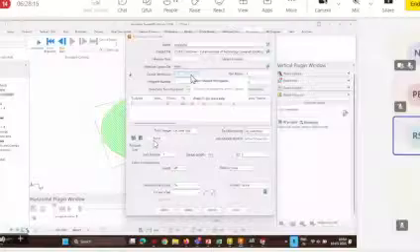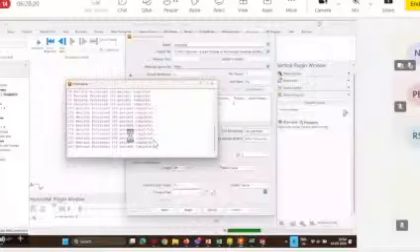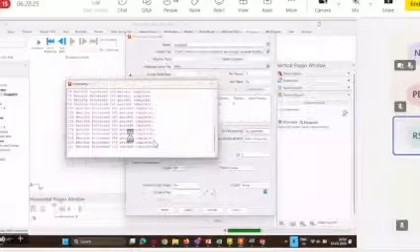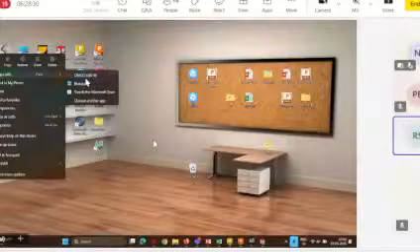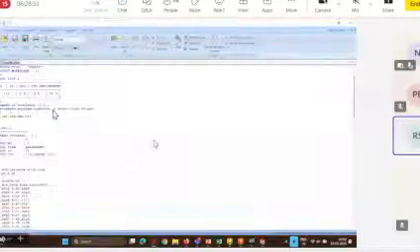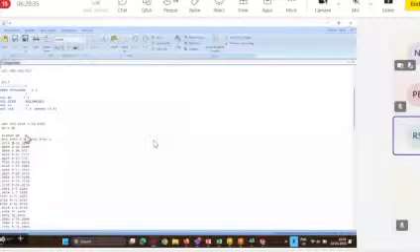And again if you go back to the desktop, the toolpath 2, if I right click and open with maybe SimCon or Notepad also, then you can see this toolpath. You can see it's having all the G codes and M codes. So now the next step is that before G01, we need to put the welding on command.